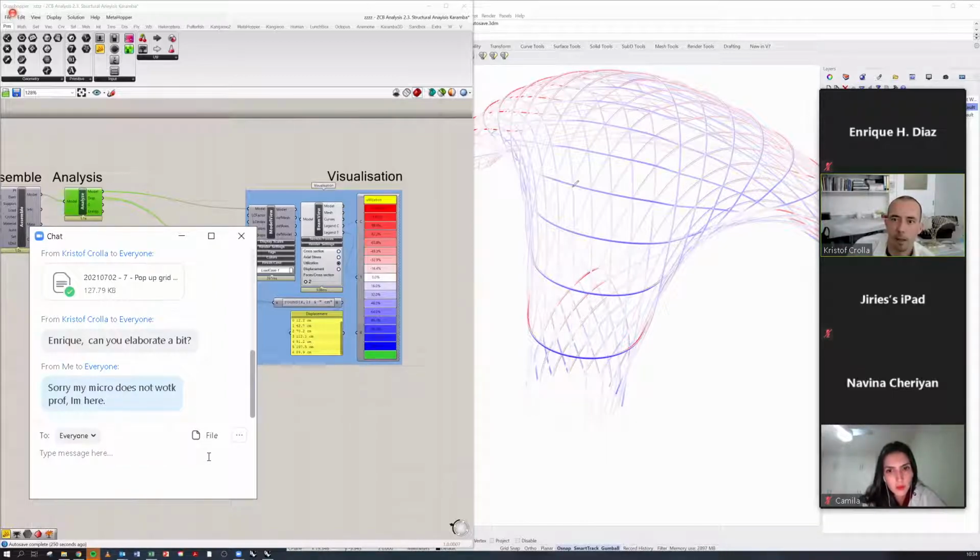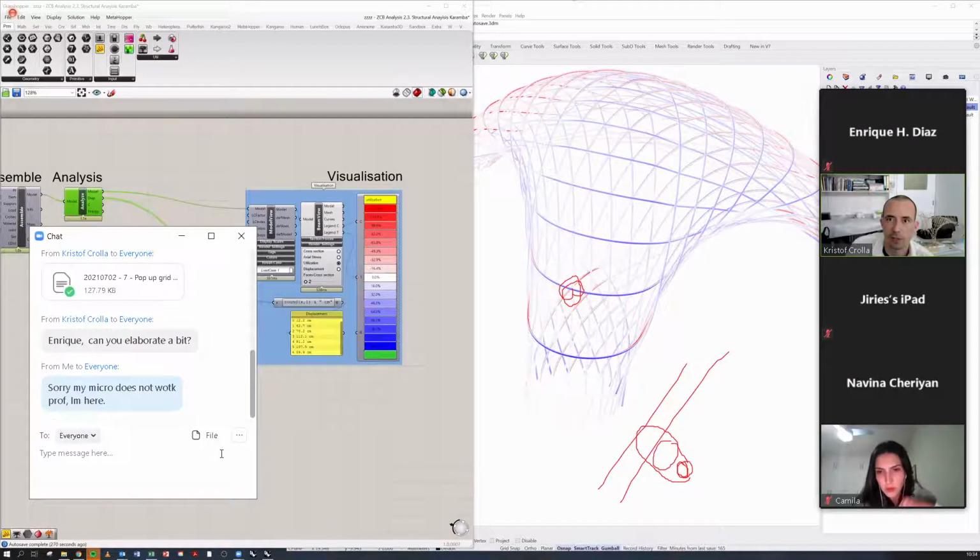Because let's say in this drawing here on the screen that all the blue ones would be steel cables instead, which would make sense for a design like that. Then in a connection like over here, if you have your two bamboo columns crossing, say like this, what you can do is fix an eyelet underneath it and tie that to the bamboo, and then have your steel cable running through that.